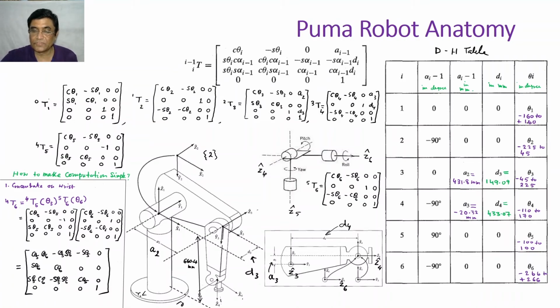Means, for example, if you stand on your own feet, you cannot rotate 360 degrees. So every joint, theta 1, theta 2, theta 3, has a range which is specified here. For example, theta 1 can rotate minus 160 to plus 160 degree. So this is all in degree. Similarly, all these have a range. So up to this, so far so good, and we'll talk about that once the structure is given, then taking the design data, you are